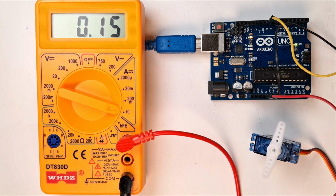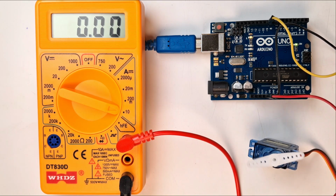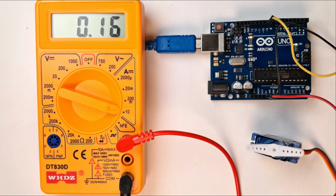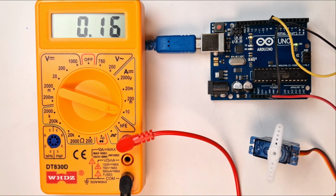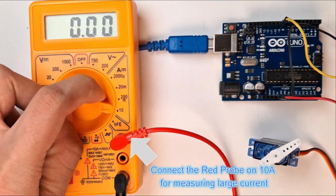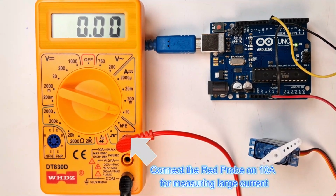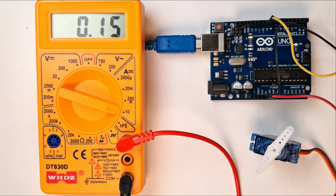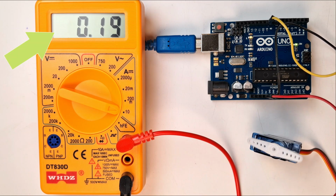For this circuit as well, the concept is the same. We have to break the circuit and connect the multimeter in between, in series with the circuit element for which we want to measure the electric current. First, make the circuit, connect the black and red probe as shown in this video, set the multimeter on 10 ampere and connect the USB cable to your laptop. You can see how much current is taken by the servo motor on this multimeter screen.